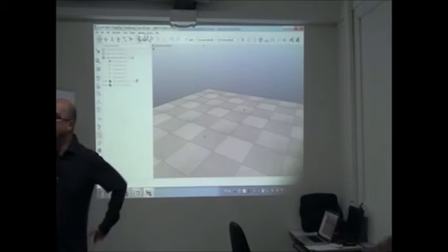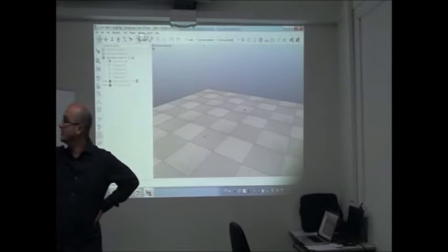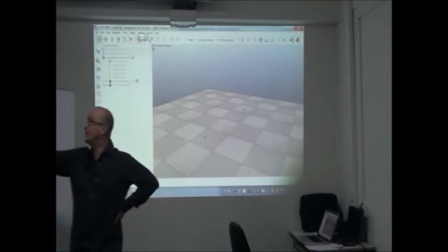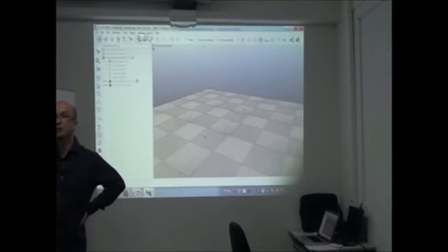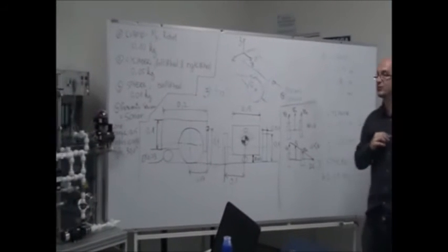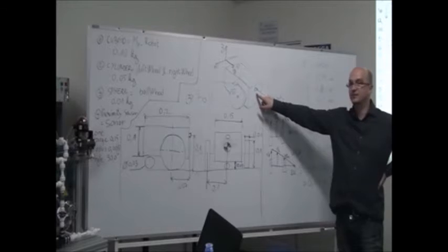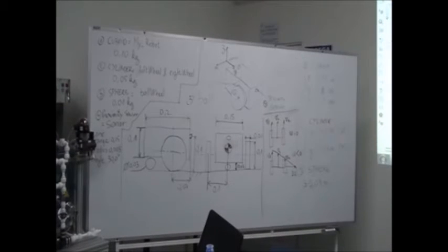So we want to design this robot. Everybody can see here. This is a differential drive robot with 2 wheels. Actually, there is a third one. We'll see why. We make it simple. It's basically a cube with 2 cylinders for the wheels, and we'll have 2 motors, left and right motors. Once we have made this model, we will change the dynamics to make it stable, and we will have our first control script to control its behavior. And also we have a proximity sensor here, which is important. Okay, let's go for it.